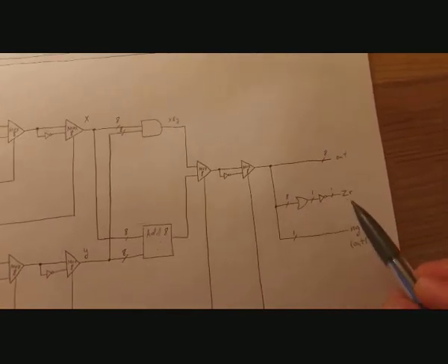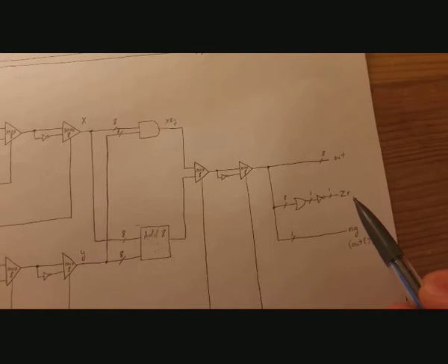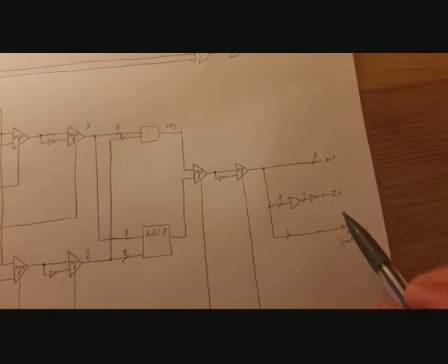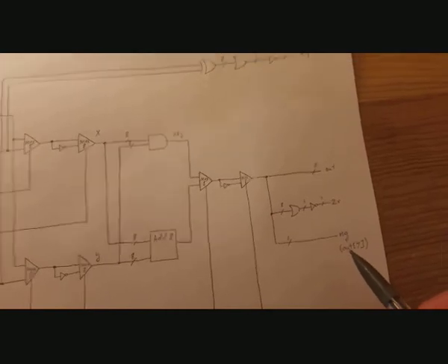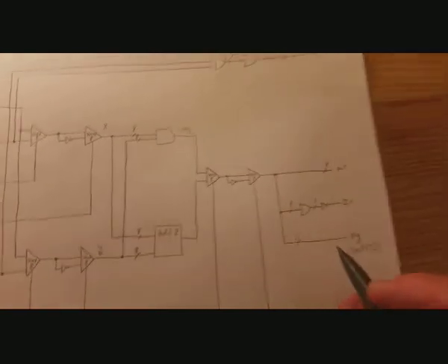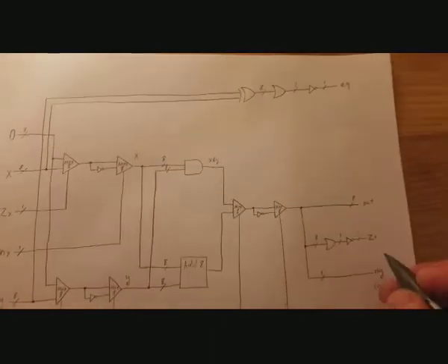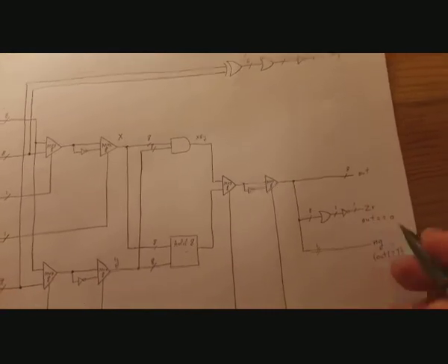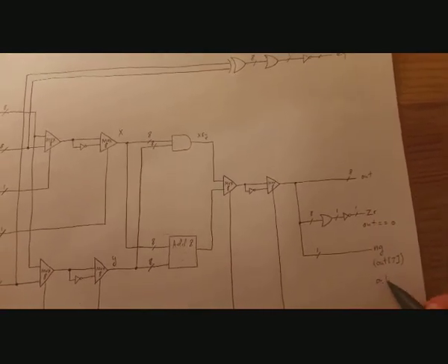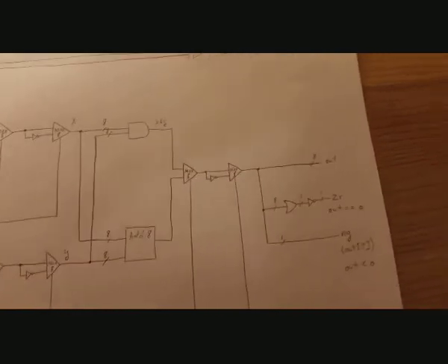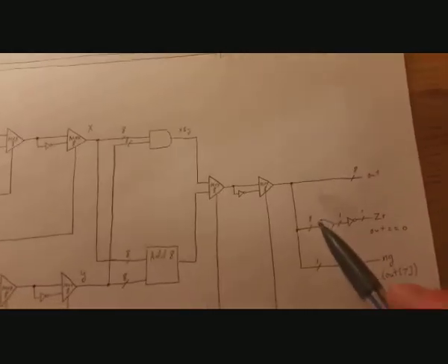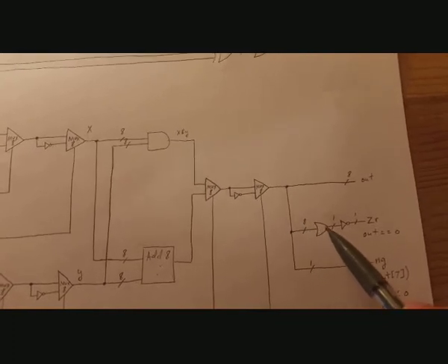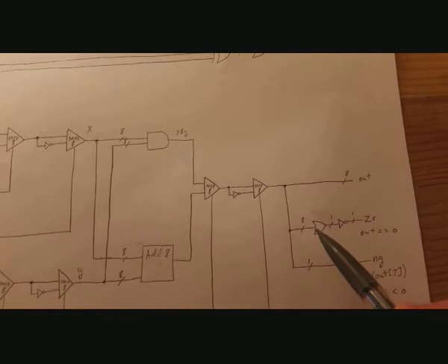These other control bits here are for determining whether or not the output is 0 and whether or not it's negative. I don't think I talked about that when we were looking at the textbook for NAND2Tetris, but if out is equal to 0, then that's going to be a 1, and if out is less than 0. So the way this is going to be done is we're going to take all the bits in the number and we're going to OR them.